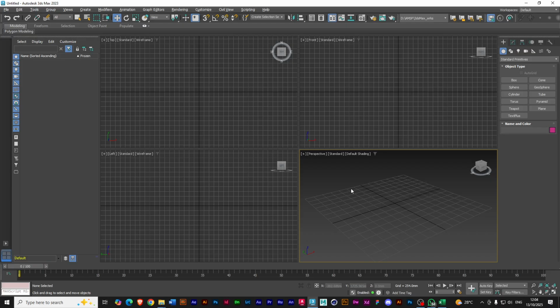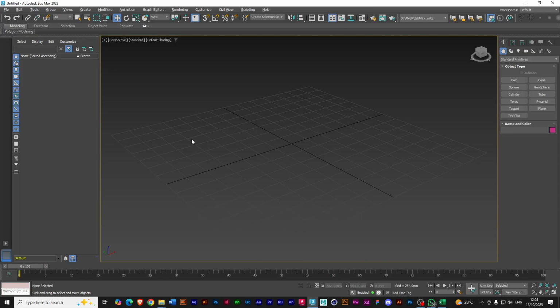So let me go into full screen with Alt W, and I want to draw a box. Now, if you click on the icon for what you want to draw, there's some other setup that comes up that allows you to determine how your drawing will look before you begin. So here I have creation method, cube and box. I have layer color, meaning as this thing is pink, the cube I'm going to draw will be pink. Not that it's the material, that's just the layer color.